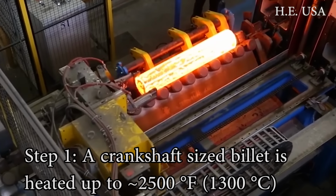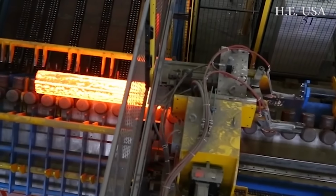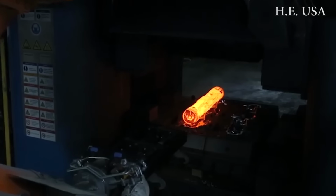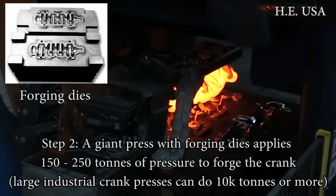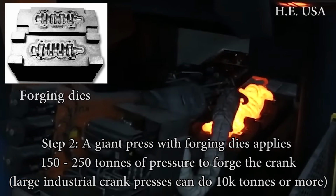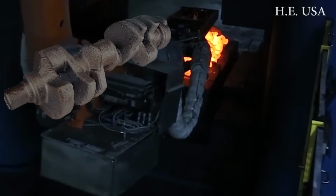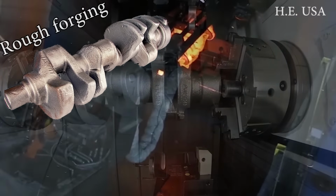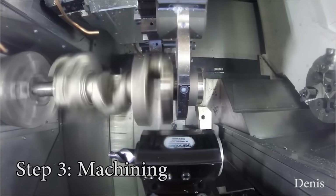The forging process involves a large crankshaft-sized billet being heated up to around 2,500 degrees Fahrenheit. The heated billet is then put in a giant press, which has dies in it. The press then applies anywhere from 150 to 250 tons of pressure to shape the billet into a rough forging. The rough forging is then machined and heat treated to produce a finished crankshaft.